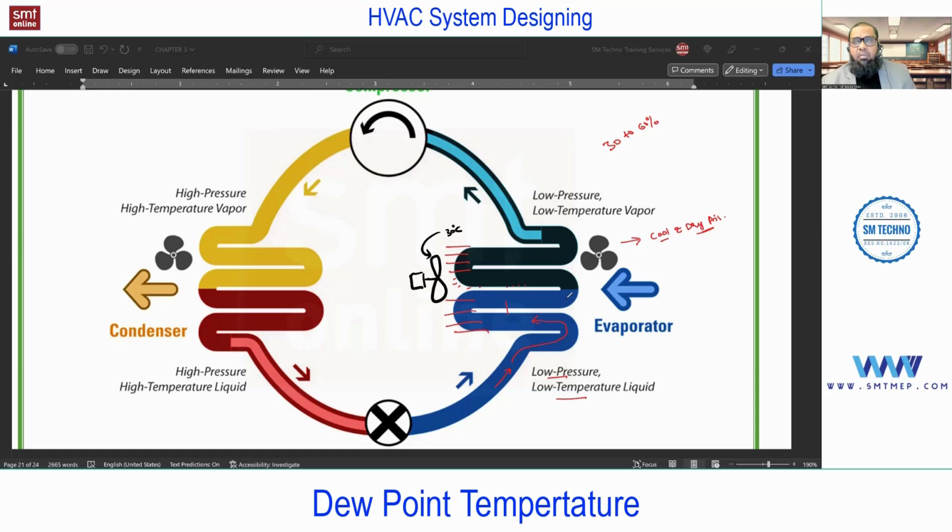And we have a standard: 1 ton will extract, if you want, you can make a note of this, we'll discuss at the time of chapter 5 also, 1 ton will extract 1.2 liters per hour. This is standard. It may vary as per the cooling capacity and as per the efficiency, but the standard from an interview point of view is that the dehumidification rate for 1 ton is 1.2 liters in 1 hour. We'll discuss more about this at the time of chapter 5.